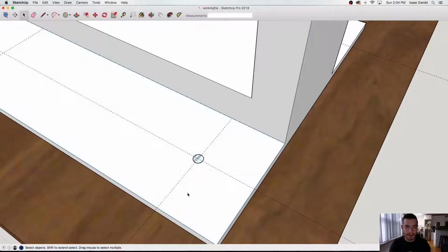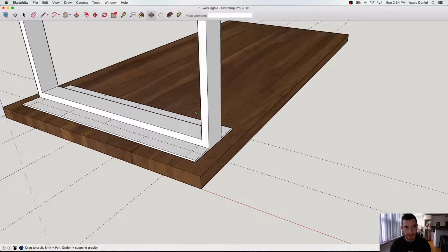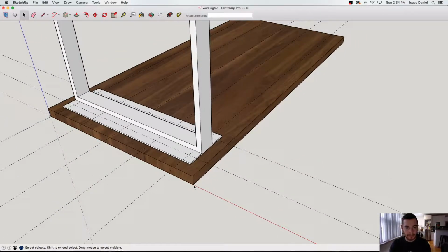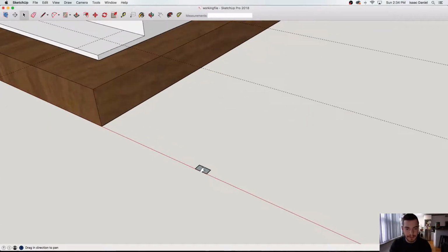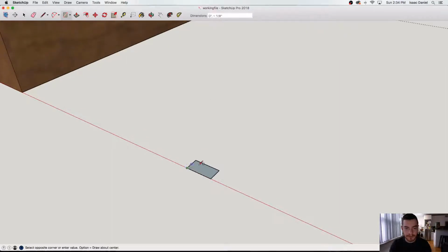I like to fabricate with slotted holes because slotted holes are better for woodworking. Might not be best for whatever application you're using it for, but I'll show you quickly how I would draw a slotted hole. Just draw a rectangle at whatever size your slot you're kind of looking for is. For us, it's probably about a 1/2 inch by 1/4 inch rectangle. I'm going to show you quickly. I'll make a bunch of lines on this, but I'll delete them later, but I'll show you why it's important.